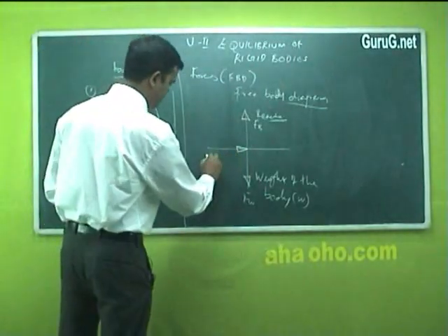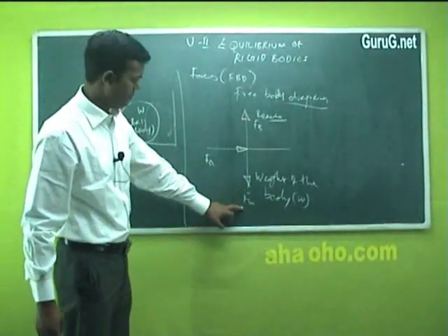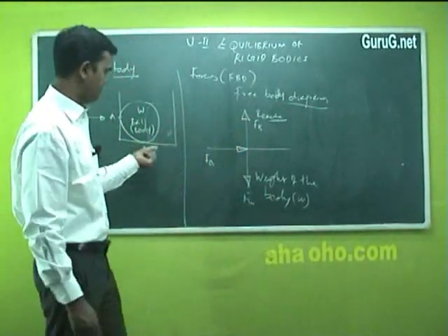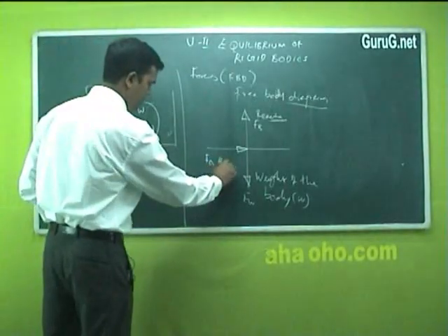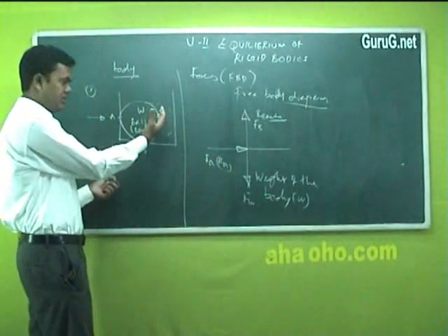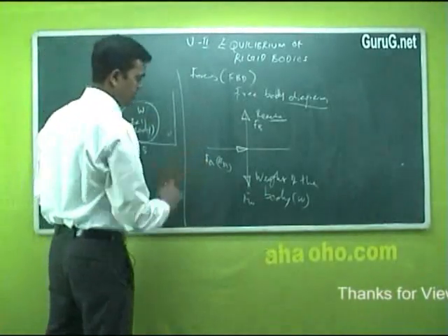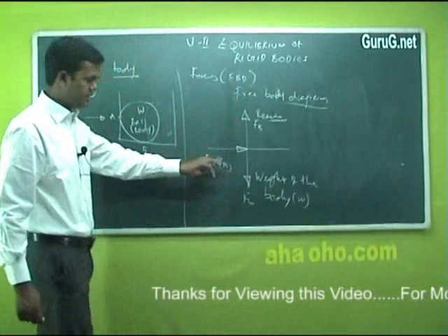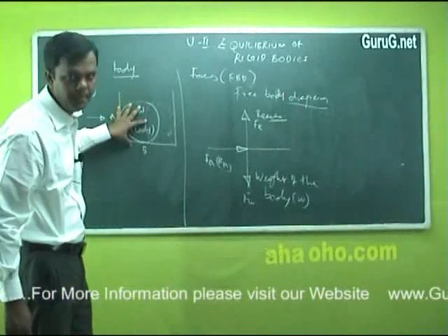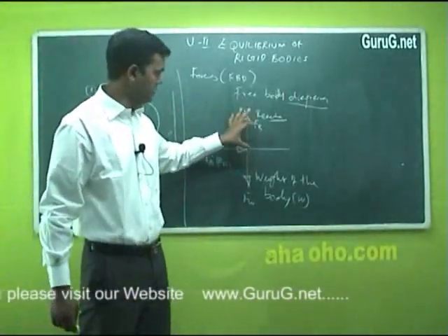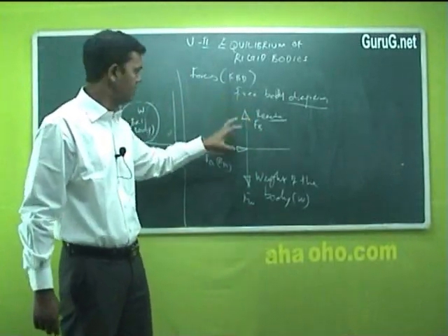So I can say this force from point A. This force A, due to self weight it is FW, and reaction from this bottom it is FB. You can take reaction for this also, no problem. Even it can be taken as RA. In the sense, there is an action, that means it is leaning towards the vertical wall, and this will give an opposite direction. So this diagram which we are drawing, this sketch, the number of forces acting on this body taken in terms of this line diagram, and this diagram where we consider only the forces directly acting on the body is known as free body diagram.